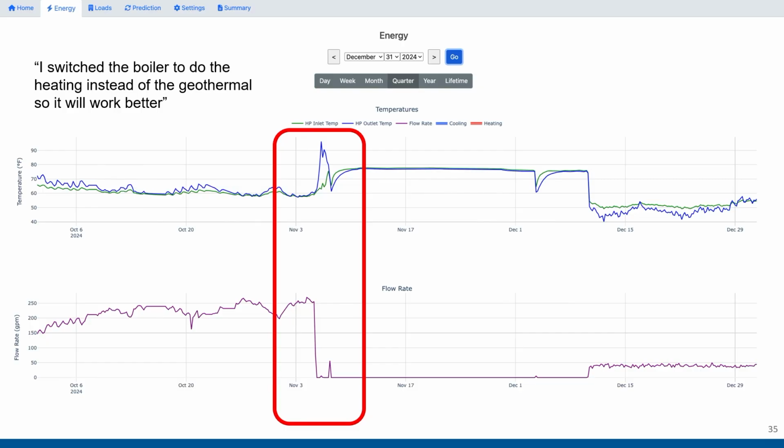But it's not that easy to figure out a good sequence that doesn't start warming the ground, and the controls contractors really don't believe that you just want it to bring the temperature up a tiny bit and let it go back. But that's a problem, figuring out a good sequence that's not going to waste energy with the backup boiler on any system.